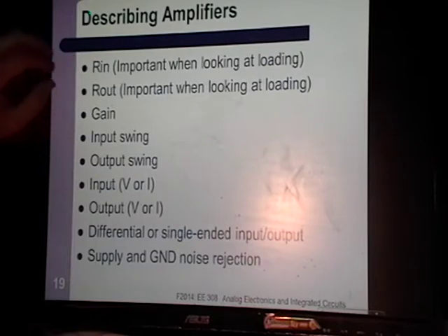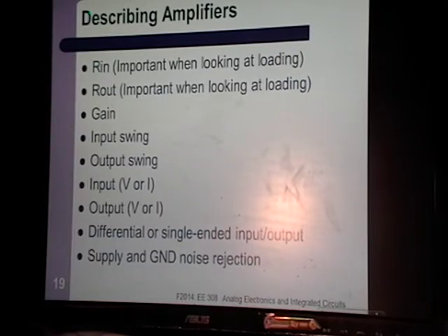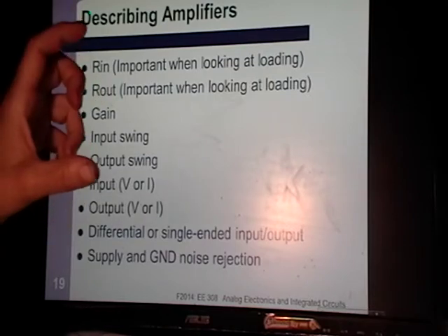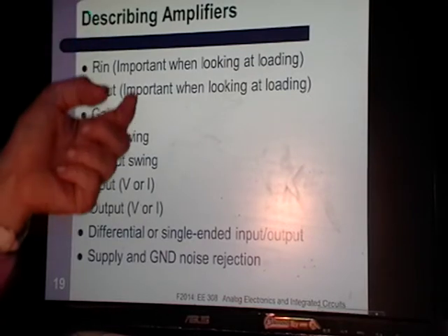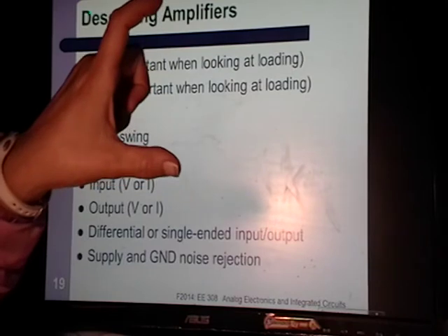But remember, I mentioned with Bosco that if you have a voltage divider going to, say, the input of a BJT, since there's a base current, some of that current gets stolen off of the voltage divider.